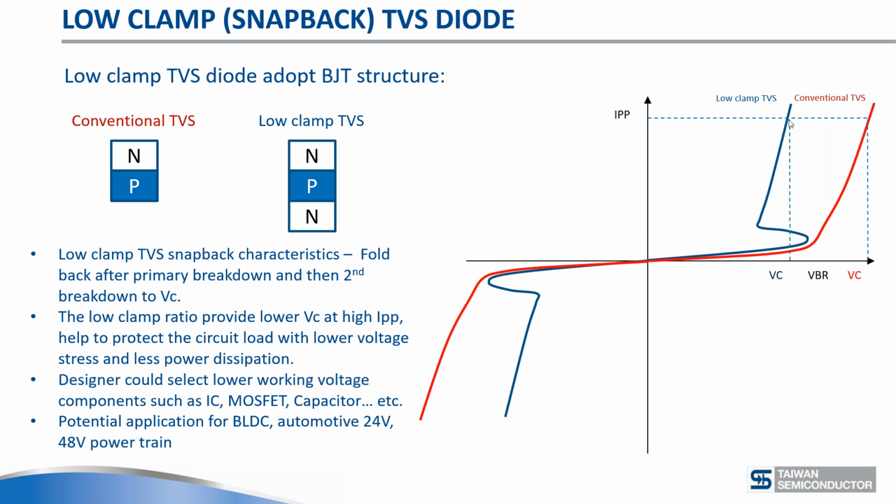And so as a result here, what you do get here is that the 30 volt MOSFETs are obviously better than 40 volt MOSFETs, and so are other things. That's the way silicon works and CMOS works here. So these are two advantages of this new technology here. Potential applications are we start with automotive 24 volt here. We may be looking also at 48 volt devices here. It's going to be a little bit different than a TVS.